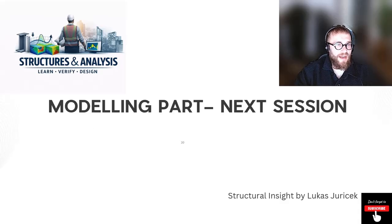In the next session, I want to focus on the modeling part, where we'll tackle the testing sample in ABAQUS, and we will do it step by step. The modeling procedure goes from the part through the material, assembling, and boundary conditions, and mostly we will get deeper into how to insert and compare the built-in damage evolution law with your predefined damage.